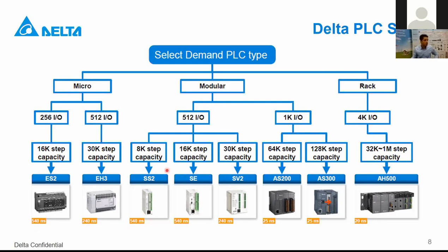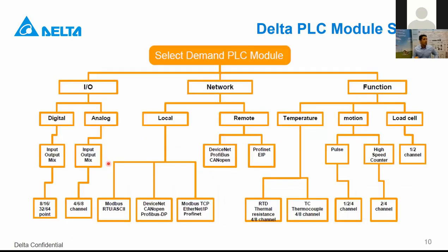And according to these 3 major factors, we can choose one of these families. Okay. And it was just for CPU, but maybe you don't know, our PLCs are modular. So choosing a CPU is not enough. We need to customize it regarding the application.